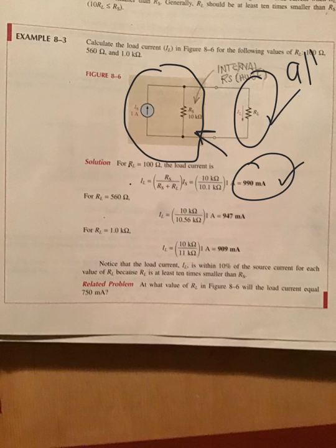And if we raise the load, now the load approaches the 10,000 of this resistance right here. It gets a little closer, which means that there's a bigger division of the current and more of it will drop into the RS resistor circled in red.